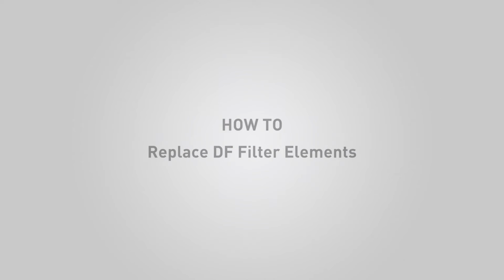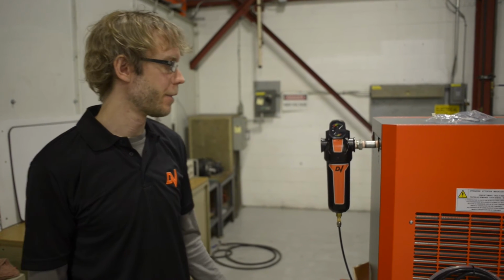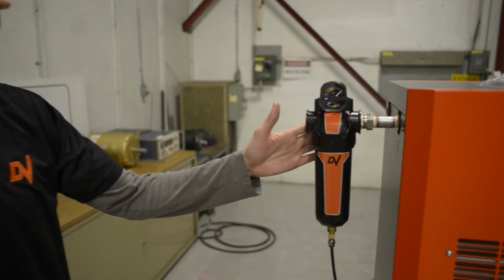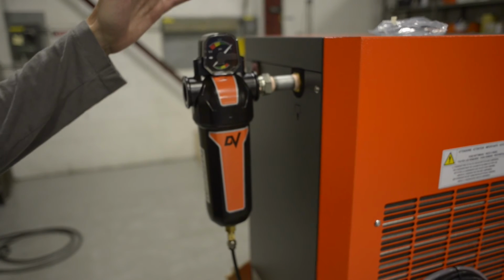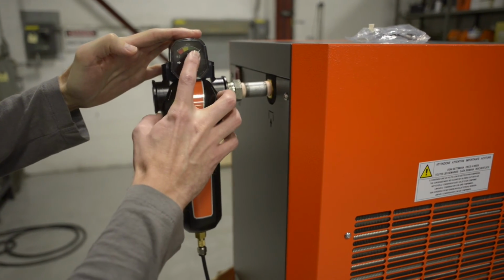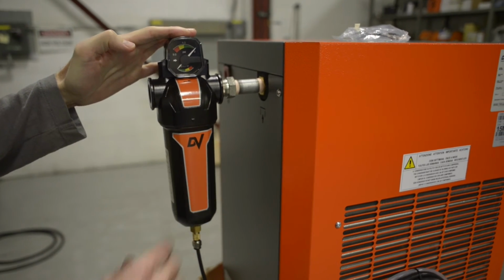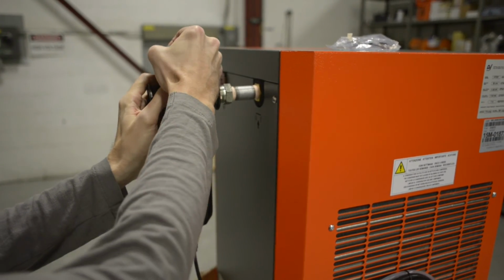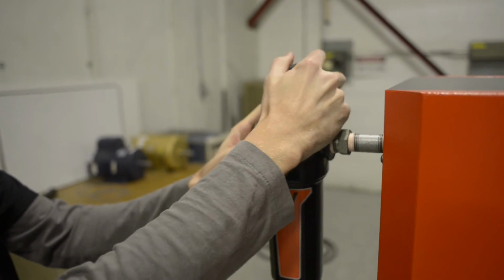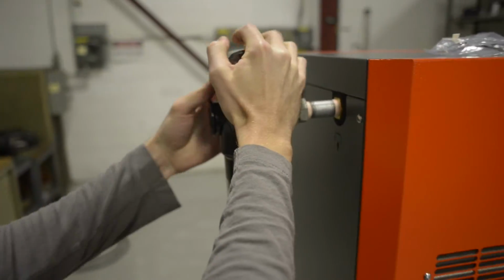Okay, so this is how to replace our filter. You see it here on a typical dryer. So we have the cast aluminum body. What you see on the top there is the dual gauge. When that needle gets to the red, that's when the filter would need to be changed. It's also removable. It can just simply clip on and off, so there's no losses through the gauge.